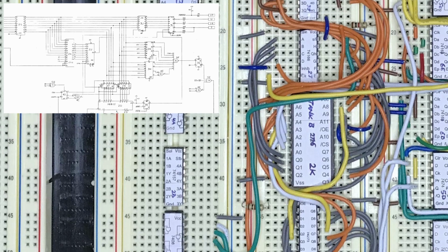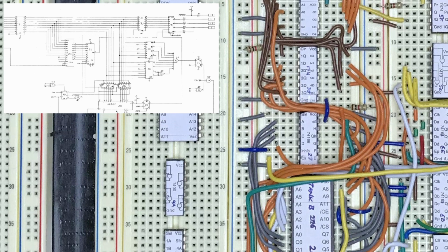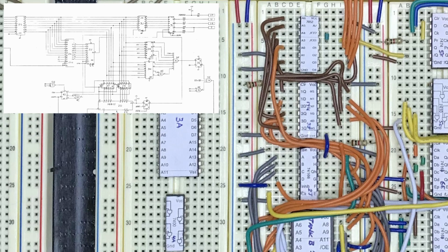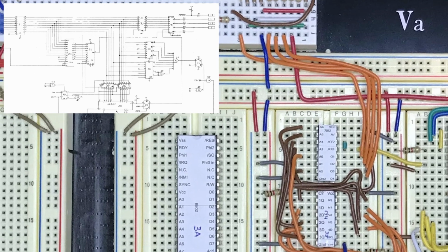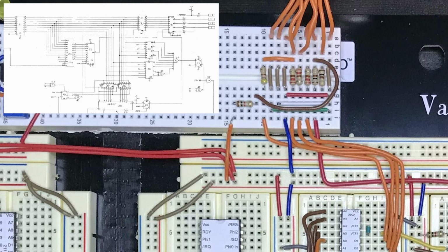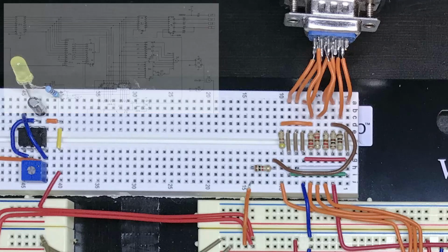Next, we have the Character EPROM. It's a bigger chip, as we'll see coming up. Then we have the 74LS166 parallel shift register to output the pixel stream. Finally, we have the 74LS174 flip-flop again, and then the 7052 or 2125 color PROM chip. That's the one that defines which color to output onto the screen. As per the last episode, we have our output hooked up to the socket connected to the PVM display.